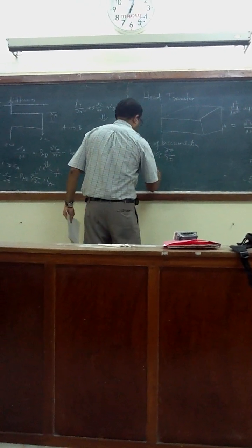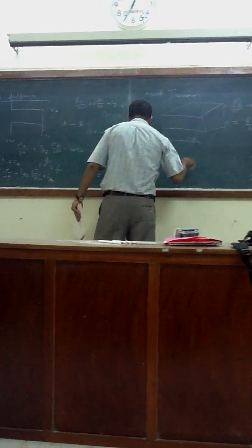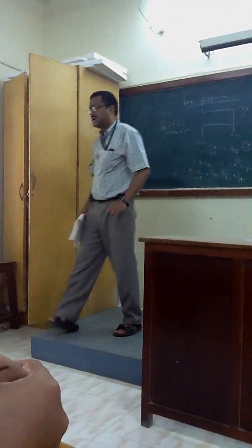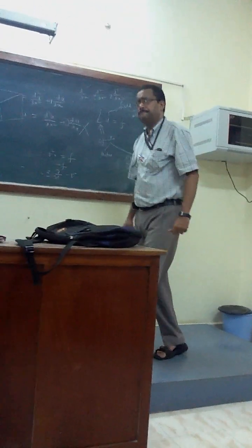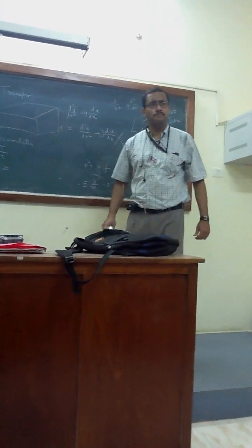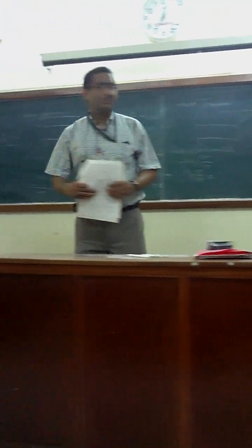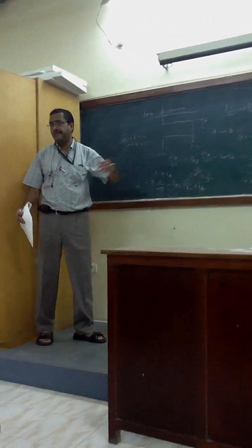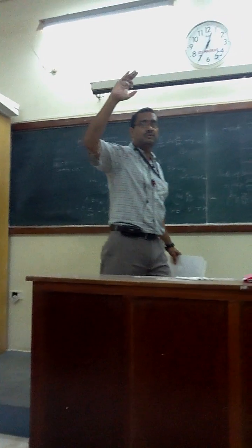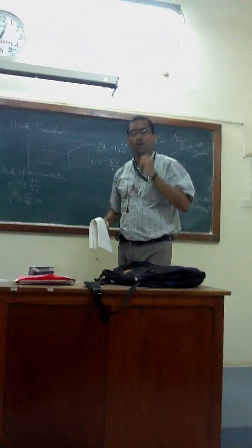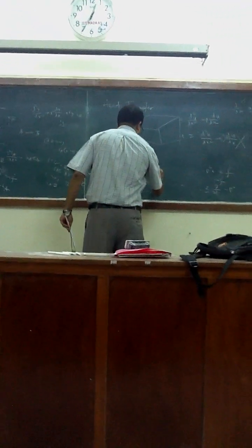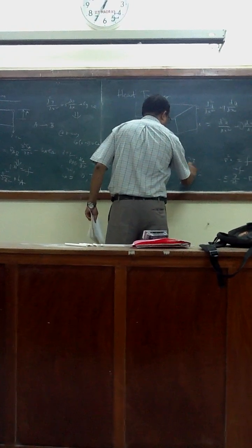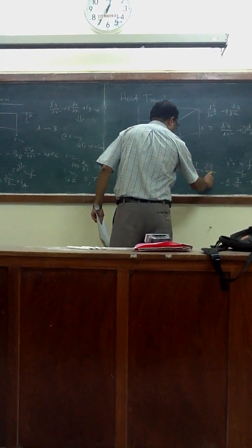What's the balance equation then? So rate in minus rate out. How do you write? You have done the shell balance equation, right? Shell heat balance or shell energy balance equation. What does it give in this term? The shell energy balance. If you look, you can get the answer. The answer is given here. What is that? Who is giving the answer? Only X, no Y, no Z. Three-dimensional. Okay. K, dou 2T by dou X square plus dou 2T by dou Y square plus dou 2T by dou Z square.